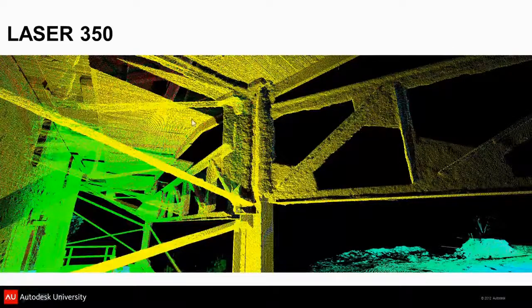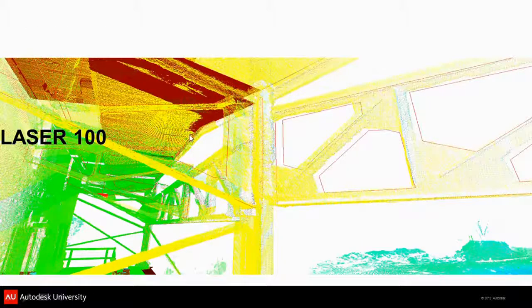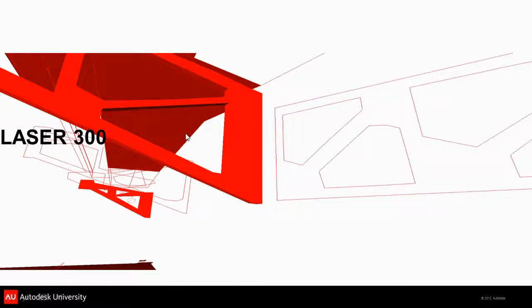What we approached in doing this was taking a laser scan, but this was the raw data. It was plate girders riveted with angles, and from our perspective, this was dense enough on high-end machines that we could actually start modeling plumbing, bring it into this laser scan model, and just use the cloud. We did not need to go to the extra step of modeling the structure from the laser. But our client, the general contractor, wanted it. So we started to look at a tool that would extrapolate the point cloud data, and then we would make massing elements. And then we'd look at how the plumbing would either connect and hang from the existing or pass through it.